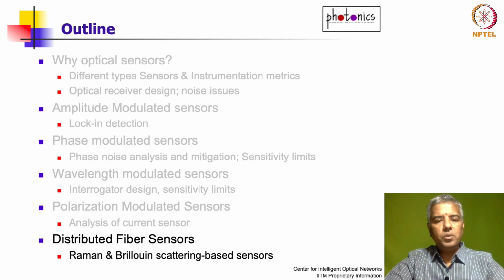So I told you previously that one of the major advantages in an optical fiber is that we can send a pulse of light down the fiber over long distances, because the fiber is relatively low loss, right, as low as 0.2 dB per kilometer. So you could possibly even go 100 kilometers and only lose 20 dB of the light, or 2 orders of magnitude of the light.